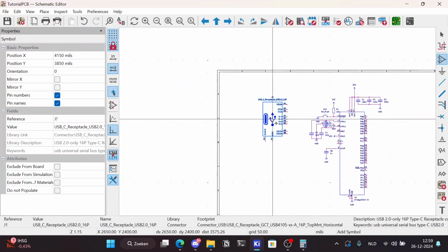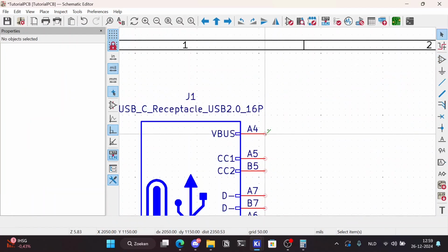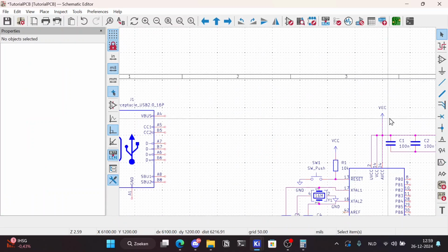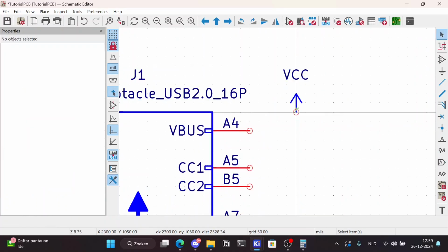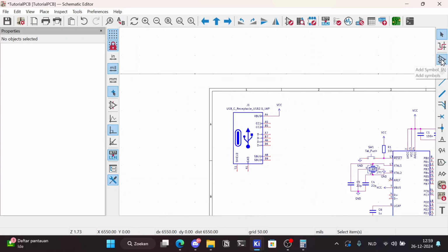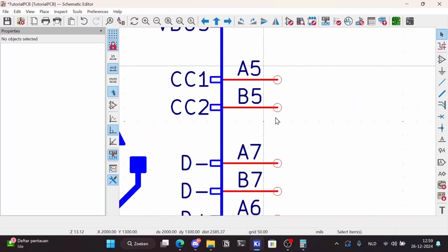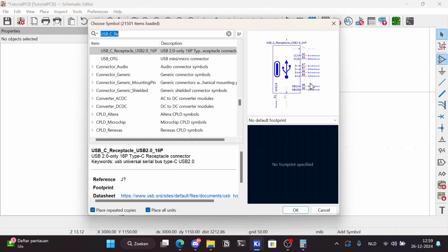So that means we go here. You can hook over VBus to VCC. However, to account for your USB-C power supply being able to output 5 volts, you're going to need 2 resistors, both of which are the same value. So to output 5 volts, you need at least 2 5.1 kilo ohm resistors.